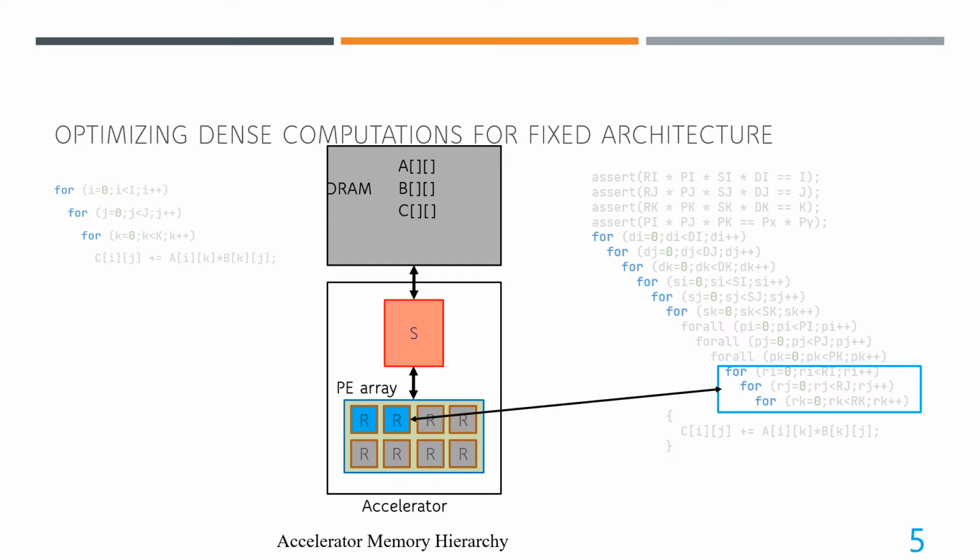Permutations of spatial loops have no significance, but the tile size selection of parallel loops does determine utilization of parallel computing resources. All other loops are executed in sequence, also called temporal loops. These loop permutations and tiling variable choices constitute different possible data flows for a given accelerator.